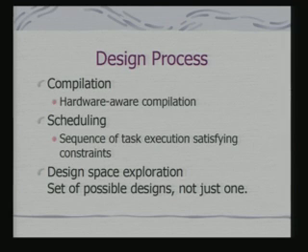Maybe the 16-bit processor with special purpose hardware finally turns out to be less costly. There may be other issues also. That means both may satisfy the timing requirements, and we would like to choose the one which is likely to consume minimum power. So, that is what we refer to as design space exploration.